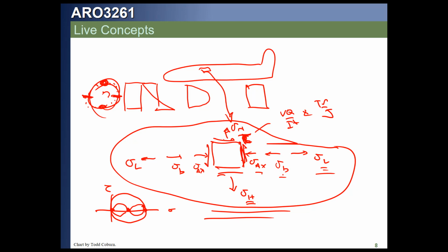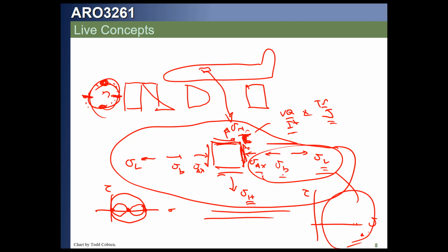But both of these will see a shear stress that's a summation of the VQ over IT and the TR over J kinds of stresses, which may mean that when we plot our Mohr's circle, we will need to come out here to whatever that stress on this face is, plot it here, and if the shear stress is like this, it plots below the axis, we plot that stress and then end up striking whatever curve we have. As we've said before, Mohr's circle is a very handy tool. It's not used a huge amount anymore in industry, but is a useful tool for evaluating stresses.